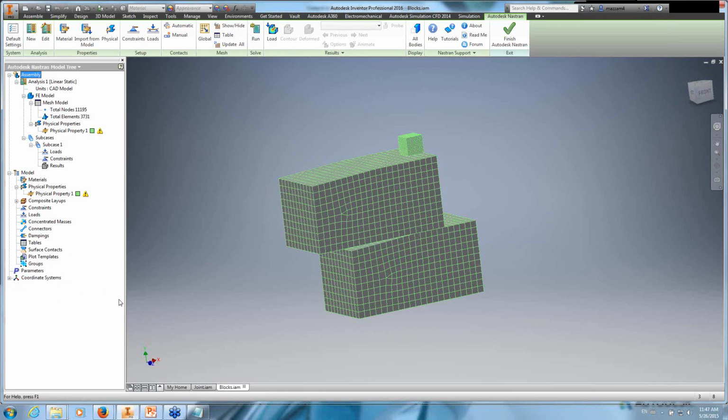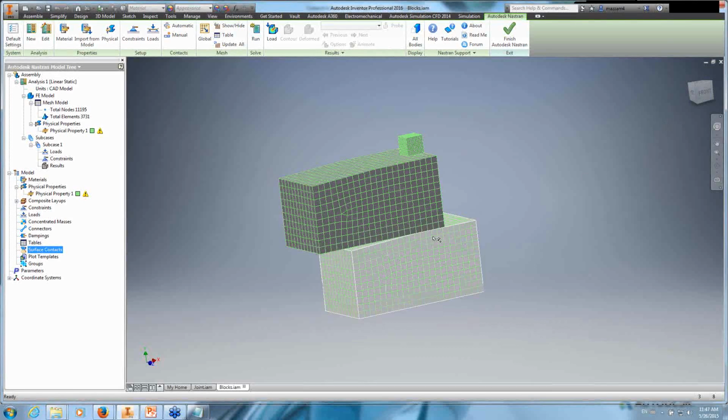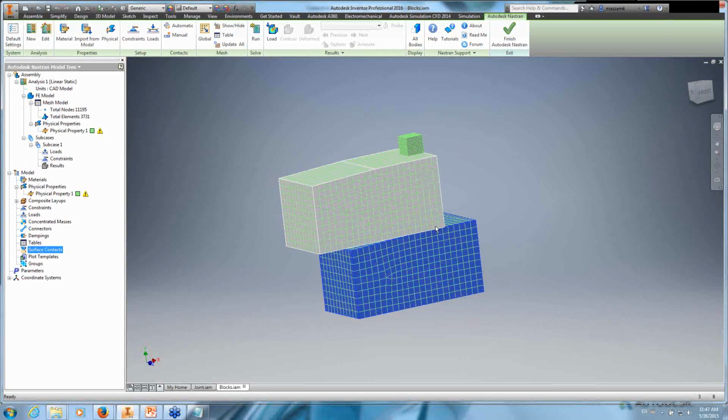So in this case, surface contact. Let's see, where's my contact setting here? Contact. Automatic, we don't want to do that. Results. So basically we want to set that it's bonded, which would bond these two surfaces and this surface here and the one under it.